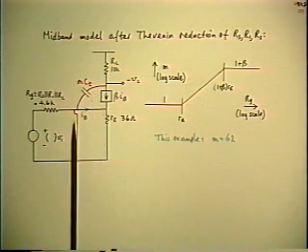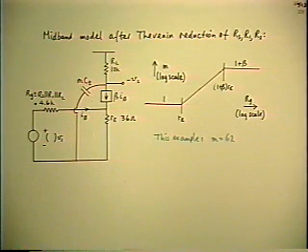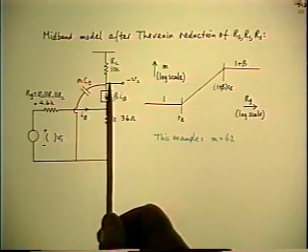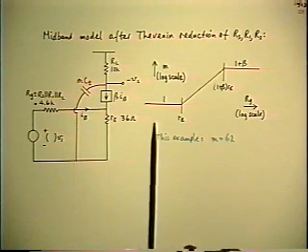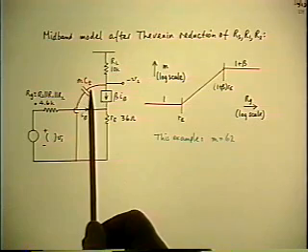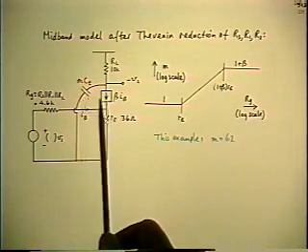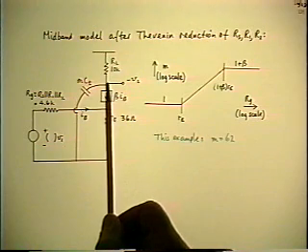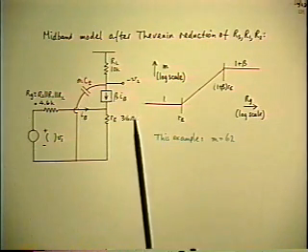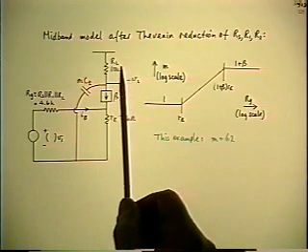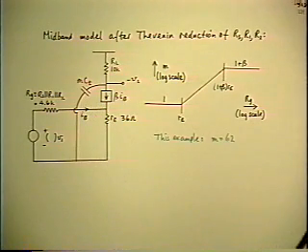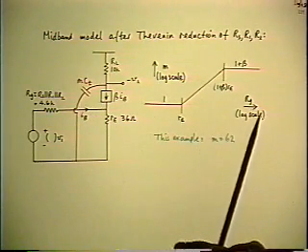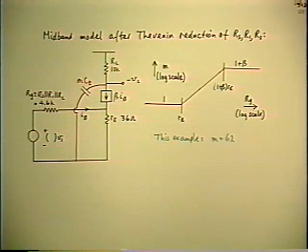Okay, notice on this picture I've made an equivalent circuit modification. I've unhooked the CT from the base and reconnected it to ground, and I can do that as long as I multiply the CT by M, because I have now placed that capacitance directly in parallel with the RL, so that if I compute the bandwidth or the corner frequency by just finding the corner of RL and this capacitance, I'm going to get the right answer for the pole, the omega 4 that we've had in the example. And in fact, that does come out to about 47 kilohertz.